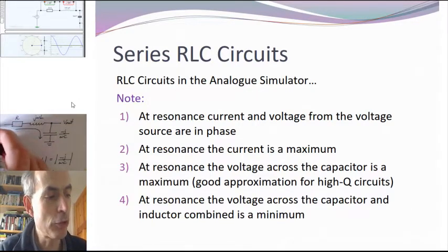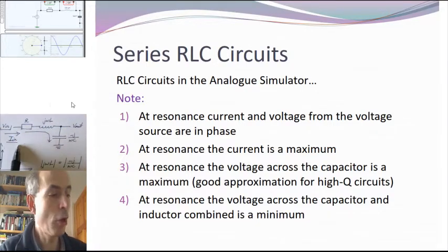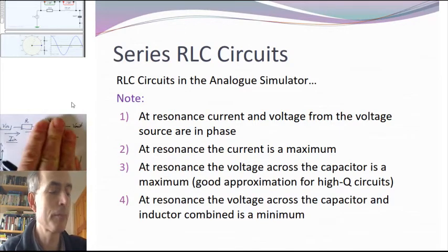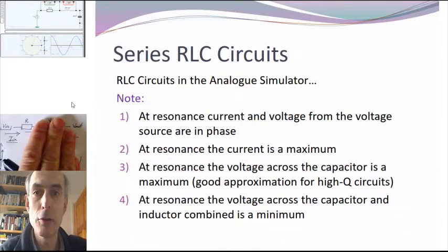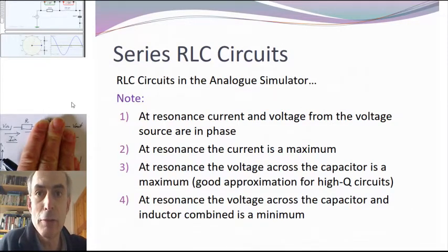That's the voltage input here and the current that's flowing in through this resistance, the input current. They are going to be in phase because the only impedance in this network is due to the resistor, and the resistor does not have an imaginary component to its complex impedance. It's just a resistance. The voltage and the current are in phase. That's what Ohm's law tells us.